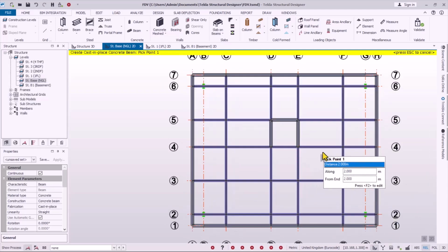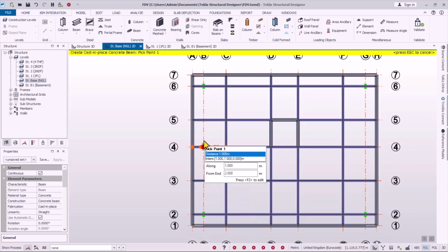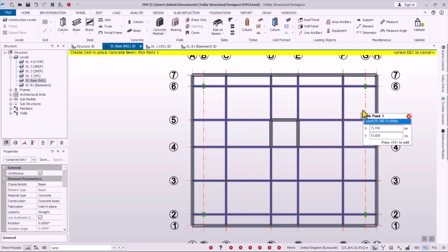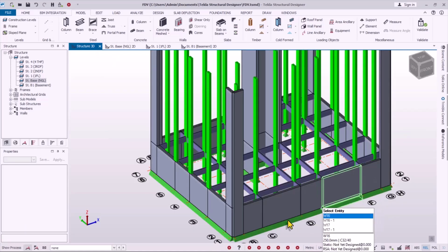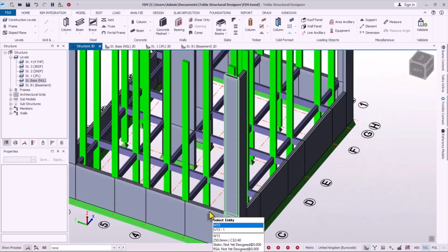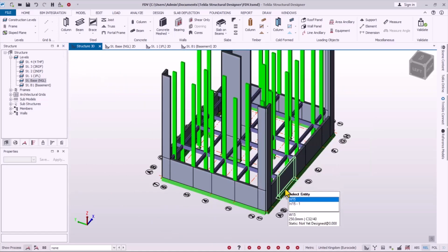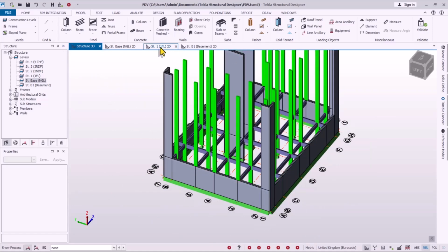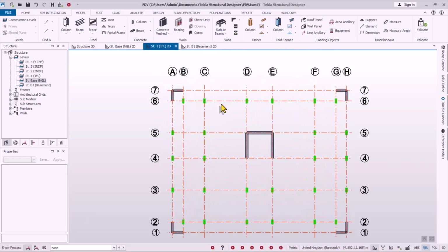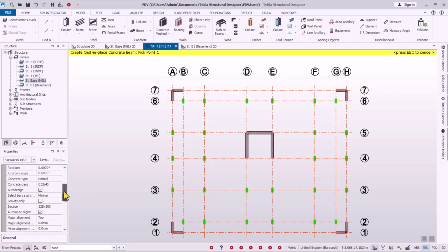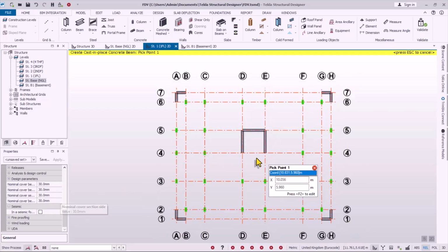Okay, so this is nice. We are done along this line. We wouldn't have beams. Okay, if you go to the 3D, this is what we get. So you can see the basement right here. All right, so now we are good. We get to the ST1, which is the first floor level. This level, we need beams right here. So click on this beam member, and then the sections we go by this. The nominal cover, this is okay.